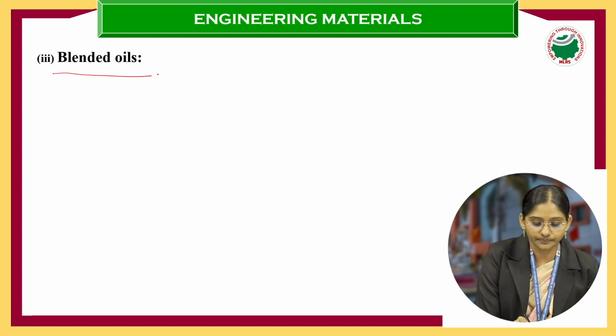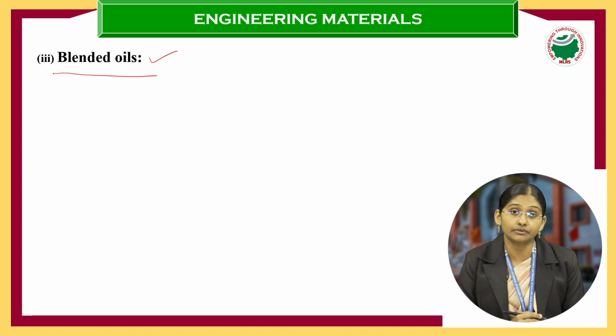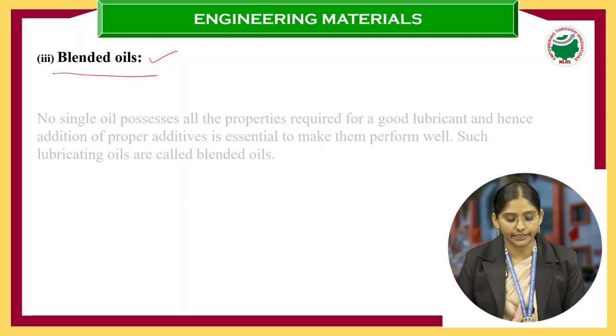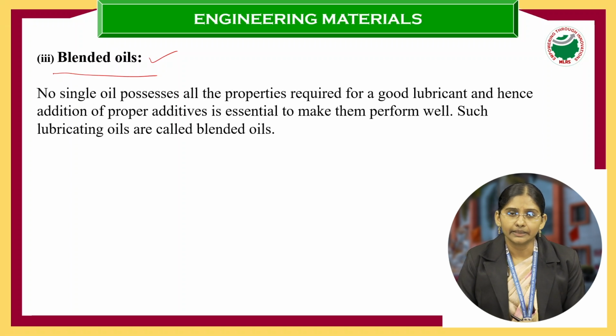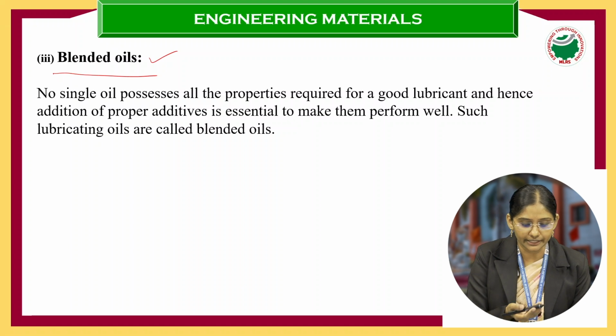Now in these liquid lubricants, the third type of oil is the blended oil. So what is meant by blended oil? What is the meaning of blending? Blending is nothing but mixing, right? So what are we mixing? We are adding additives to the lubricating oil, or the mineral oil.